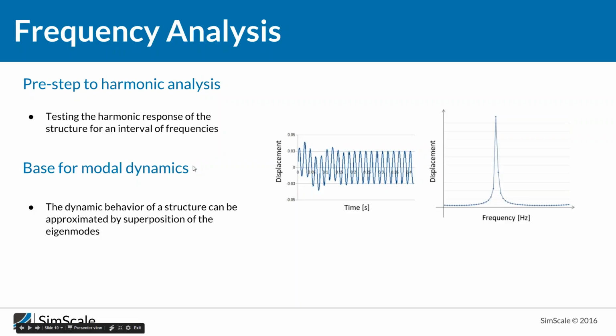And the second one I just want to mention here is that based on those eigenmodes, those eigenmovements of the structure, you can also assume that the displacement you have in a dynamic analysis can be created by a superposition of all of those different eigenmodes. Of course, we cannot calculate an infinite number of eigenmodes, but up to a certain degree you can measure how accurate it becomes.